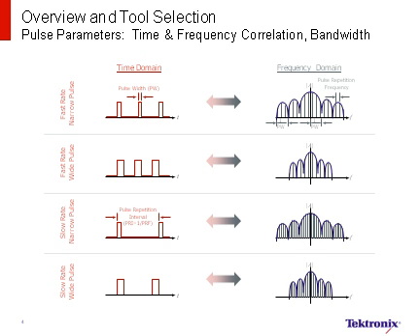The time domain characteristics of the pulse naturally have their frequency domain equivalents. A narrow pulse width has a broader spectral shape than a wide pulse width. Similarly, a higher pulse repetition frequency will have larger spaces between the spectral line components than a slower PRF. Using a traditional spectrum analyzer for these measurements, you may already be familiar with this phenomenon.